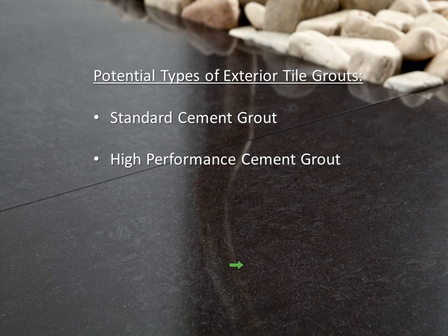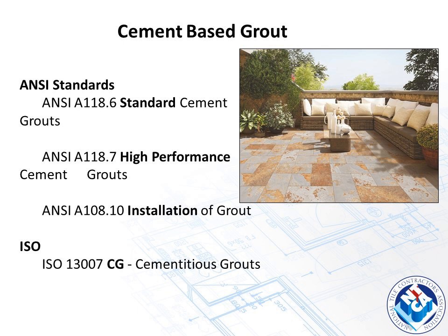Talk a little bit about grout. There's standard cement type grout, sanded, unsanded, and of course high performance ANSI 118.7 type grouts. There's the installation of grout, some of the important ANSI standards, and of course the ISO designation for cementitious type grouts.